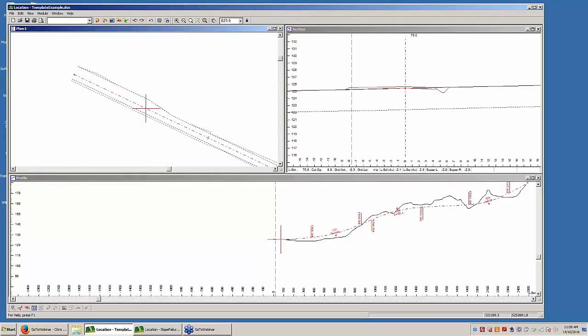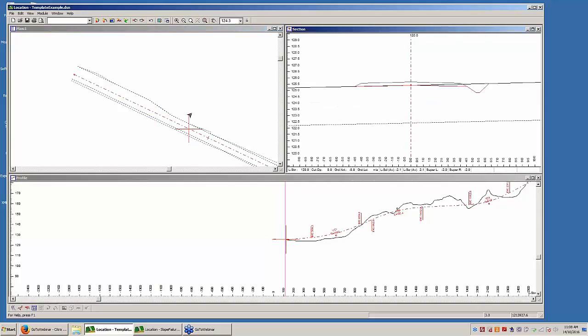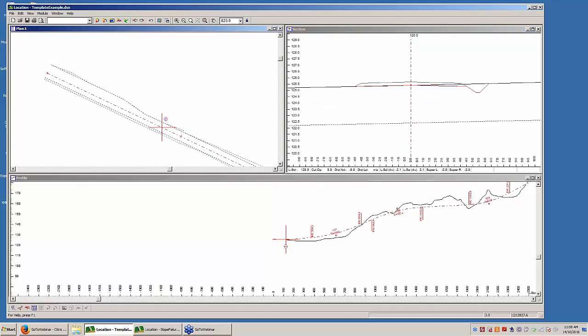And now I've got, from 0 to 75, my new road widening left template. From 75 to 100, I'm tapering it back into my default template. So if the taper was longer, you'd see the road width transitioning, and then back to the non-transition zone. Here's back to my default template. Okay, so that's pretty straightforward, and I'm sure many of you know about that already.